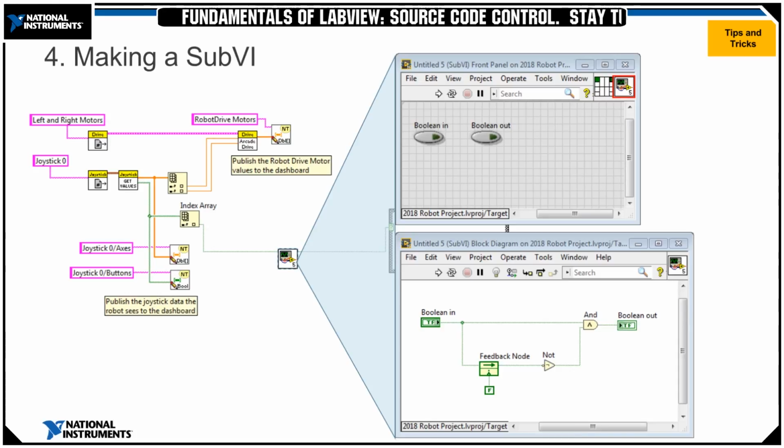So the last thing we would need to do, and we would want to do this if we made a sub-VI kind of by ourselves, is click on the sub-VI icon in the top right-hand corner. You can see in this picture that it's kind of a generic icon, it's got some LabVIEW looking symbols on it and a number. This just happened to be the 5th sub-VI I made when I was making this example, but we want to double click on that, and that will bring up the sub-VI icon editor.